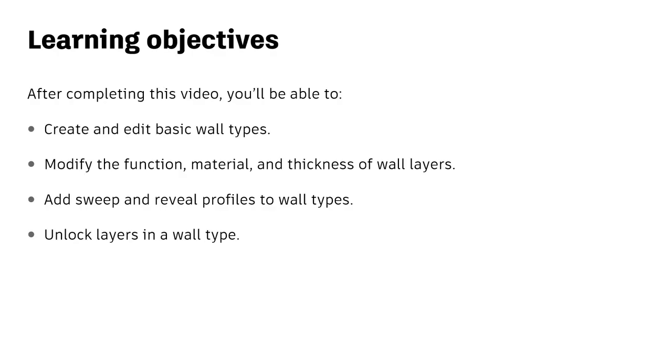In this video, you'll learn how to create and edit basic wall types, and more specifically, you'll create a brick-on-metal stud wall type and define the layer materials and thicknesses. You'll then see how to further customize wall types and use them in a project.